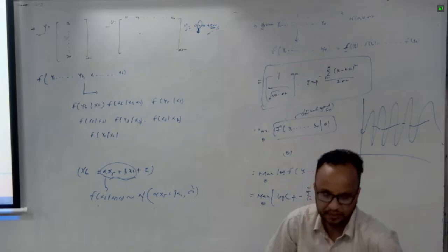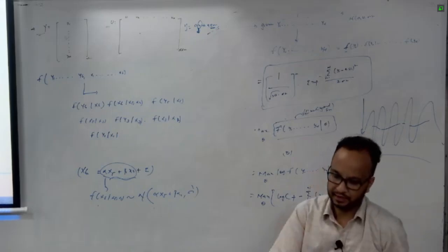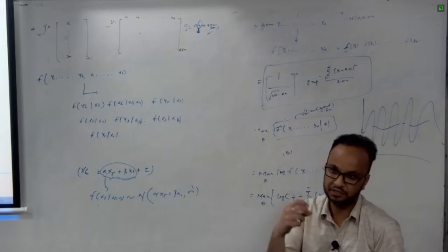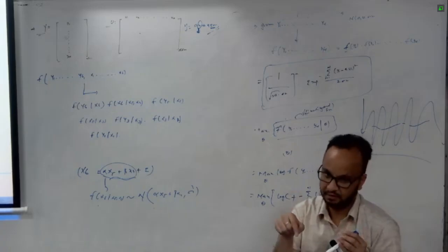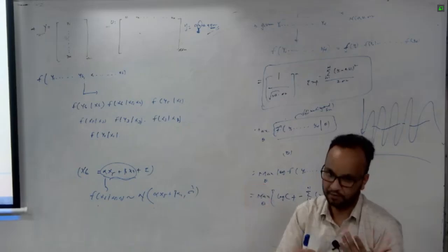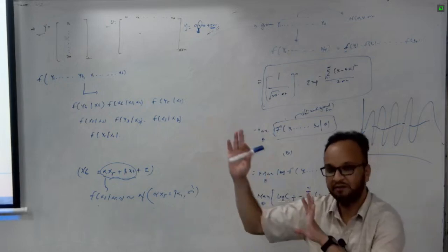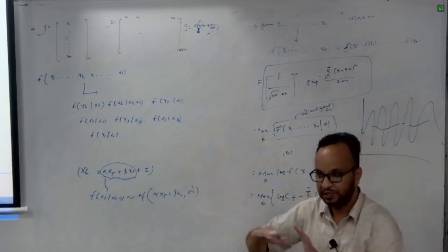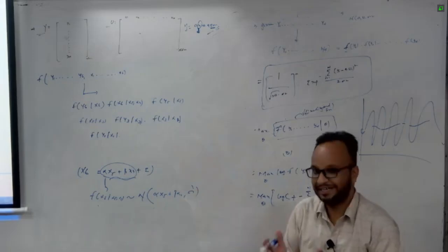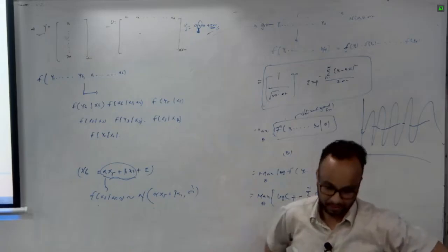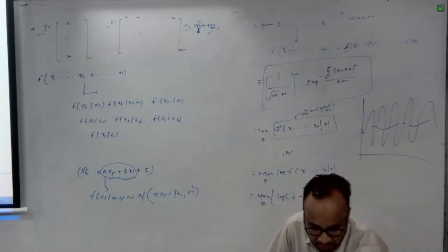Actually, in chemical engineering, say you are taking one particular sensor and your hidden variable is something you don't know inside. You need to estimate the hidden value theta because the actual sensor is giving noisy readings. So how do I estimate it? One way is filtering, Kalman filtering. What we are doing is kind of a Kalman filtering only, a data-driven Kalman filter. If you derive every equation, you are going to get a nice steady-state Kalman filter, which those who know Kalman filters can appreciate. In that way you maximize and get the theta.